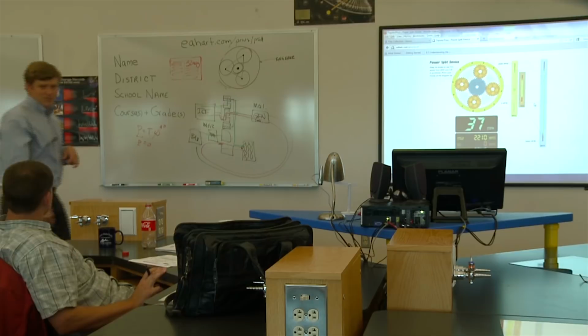Both electric motors in a Prius are permanent magnet, 4-quadrant electric motors. The inverter takes in DC from the battery and makes a variable frequency AC to control the electric motor, and it can control it in both positive and negative, in both regen and motoring.